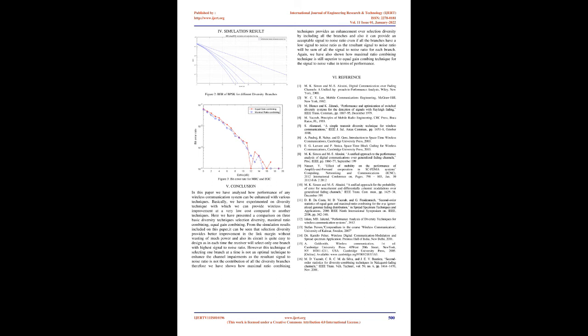C. Equal gain combining. We do not always have the variable weighting capability necessary for accurate maximal ratio combining. In such instances, the branch weights are all set to 1, but the signals from each branch are co-phased to offer equal gain combining diversity. This permits the receiver to take advantage of signals received on each branch simultaneously.